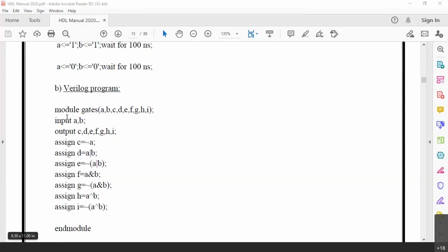We will not have any sequential assignment here in today's experiment because we are dealing with the combinational logic only. As you already know, all combinational logic has concurrent execution, means as soon as an input changes, instantaneously the output changes, except for the propagation delay of the gates. That is called concurrent execution.